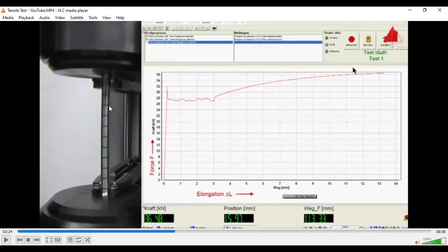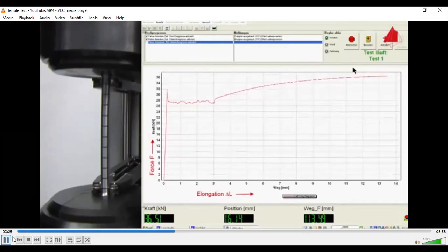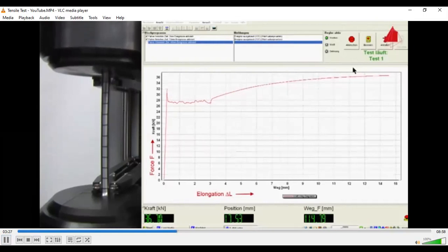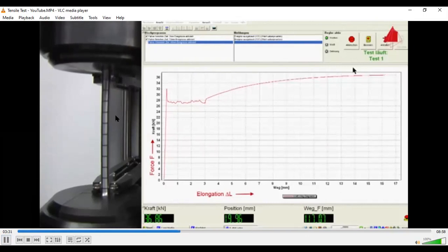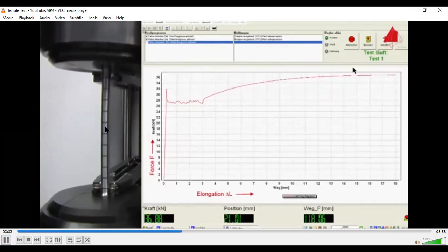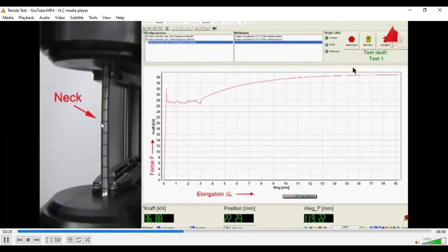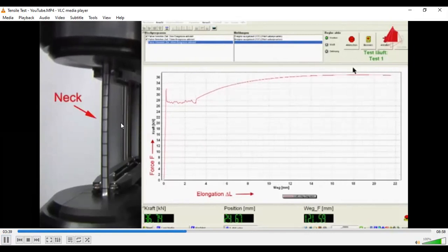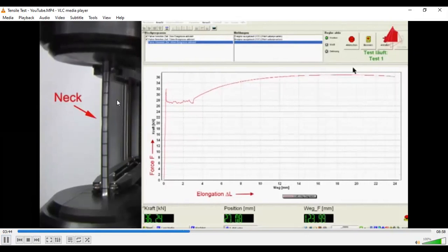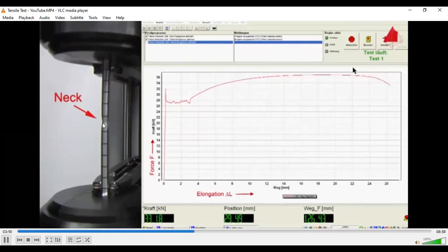We are looking at the point where the shape deforms or it breaks. This is the tensile strength. Okay, we are extending it, still it is fine. As soon as the maximum force is reached, a neck begins to form at one point of the test piece. All further plastic deformation now only takes place at the neck, and eventually the test piece fractures there. Here it is. So tensile strength is the maximum force where it starts to deform at this point.